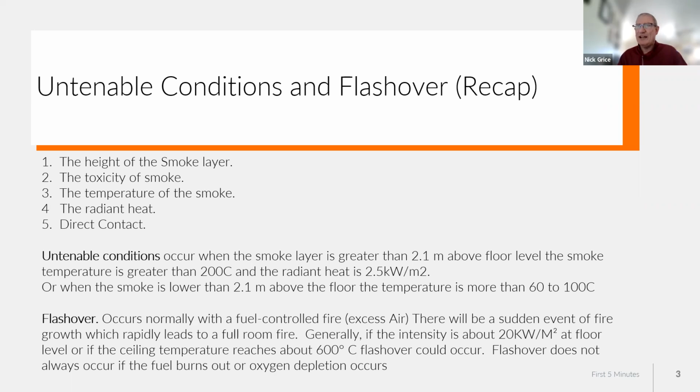The fire service have other tenable conditions, which obviously are a lot lower than that because they've got their firefighting gear. And flashover, if you remember, is what we call a fuel control fire, when you've got an excess of air coming in. So you've got loads of air coming in, feeding the fire. You get the temperature of the smoke up to around 600 degrees C, bang, flashover occurs in the room. And that's what smoke management systems try to prevent.